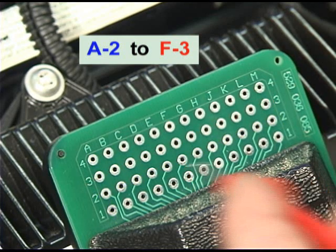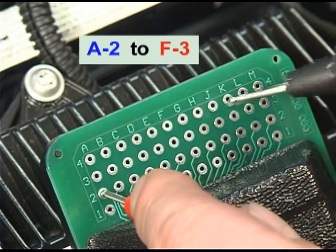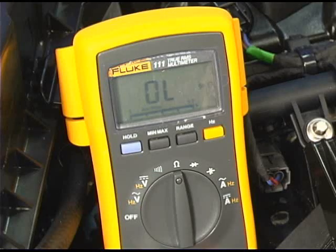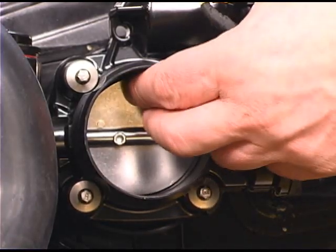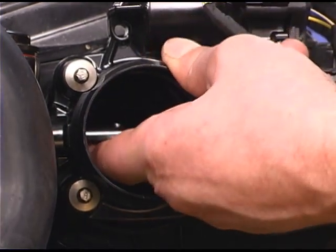Touch the meter probes between these two test points. Be careful to observe the correct polarity if the shop manual specifies it. Observe the meter reading and compare it to the specification in the shop manual. Note in this test the throttle plate must be fully closed for one check and fully open for the other.